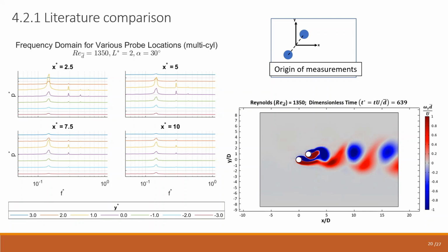For this particular configuration, there is a small gap between the cylinders which allows the fluid to accelerate. This creates a large trailing vortex in the wake of the cylinders. This is the reason you see 2 or more dominant frequencies.